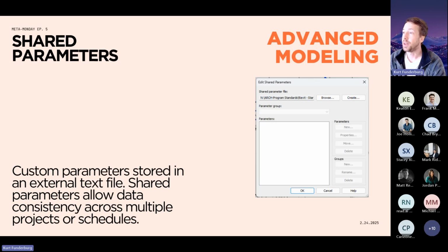And so as we develop these things, we can start to think about, okay, I want this to be consistent across all projects. That's going to be a shared parameter. That way, when we schedule things, it's always looking at the exact same parameter. And so these are things that we develop, we can talk about, but a lot of this is very much, hey, let's talk about this before we just start making shared parameters.